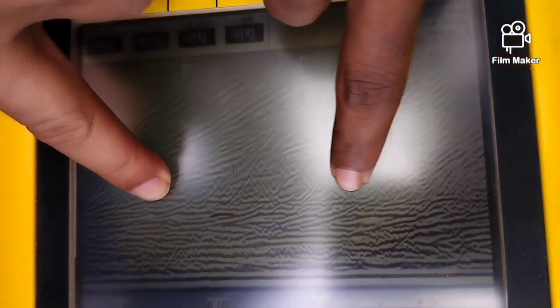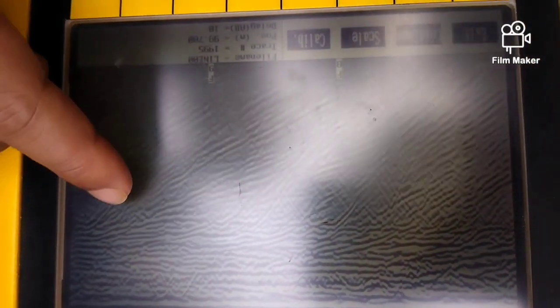So, can anyone see where the water table is in this case? Yes, that's the water table. Okay, let's pause it. Why do you say this is the water table? Lines are closer. It's looking continuous. Yeah, so all the laminations that you see up to that line are continuing across. If it were some layer coming across, it would truncate. You won't go through that. But in this case, you can see everything is coming across. So that's why it's the water table. Let's keep it going. You can see it more clear.